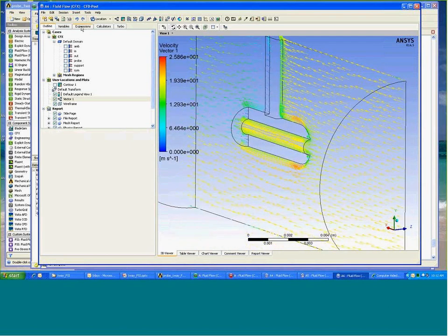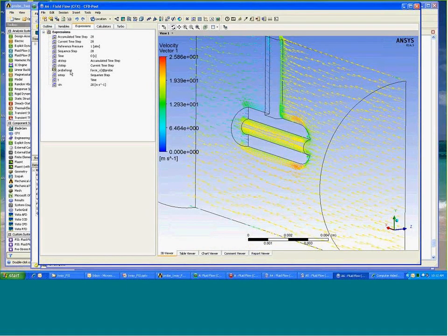As the output parameter, I defined the probe force acting on the probe. I can use that as a Workbench parameter, and later as the parameter to optimize the design in a design optimization or design iteration analysis. You can set this up easily.